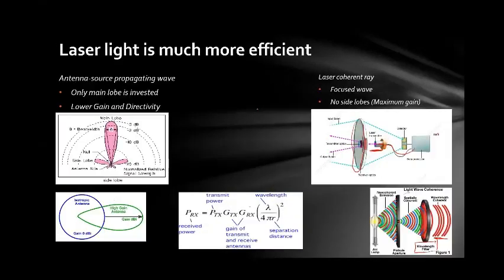So the real fun starts with this slide. And before diving deep into the details, let's establish the relationship between the wavelength and the physical size of the antenna. The relationship is as follows. The physical size of an antenna is directly proportional to the wavelength, which means a higher wavelength needs a higher physical size for the antenna.